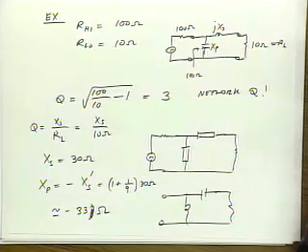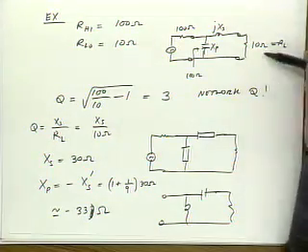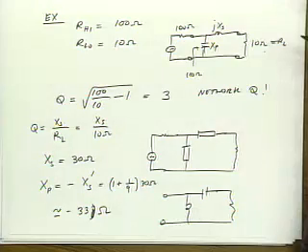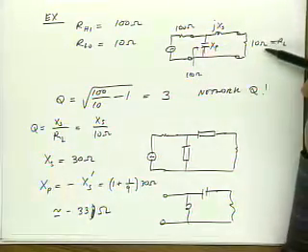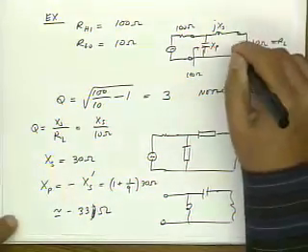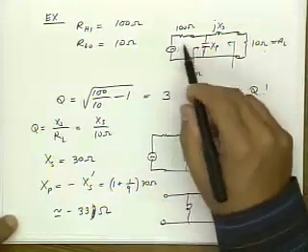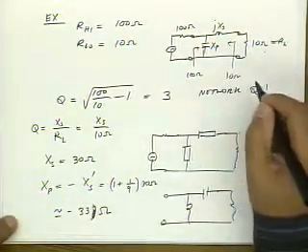Okay, well, this is a nice way of taking a low impedance and making it high impedance. What about the reverse process? How do I make a high impedance a low impedance? Any guesses? Yeah, the other way around, right? In fact, this is a symmetric network, right? It transforms 10 ohms to 100 ohms. But if I look here, it also transforms 100 ohms into 10 ohms, right?